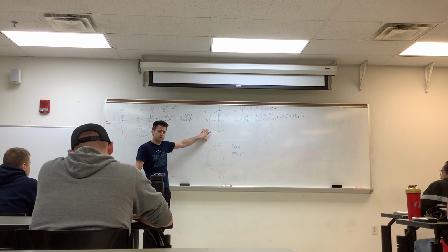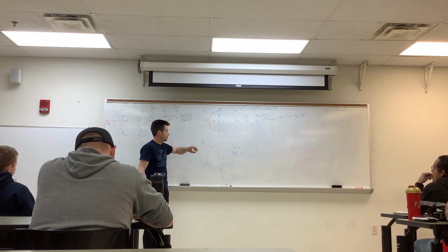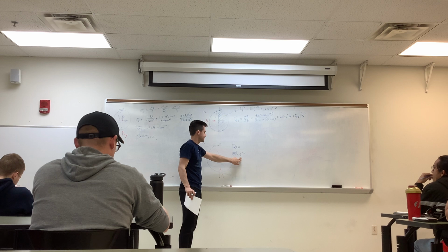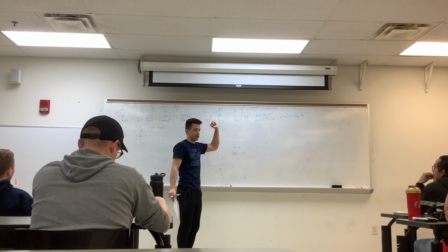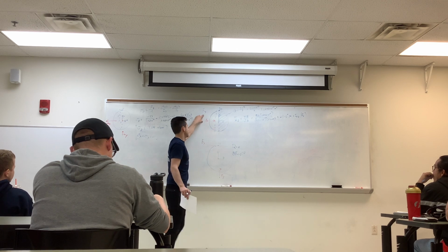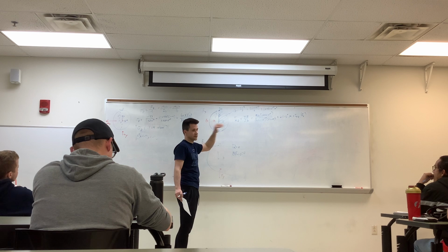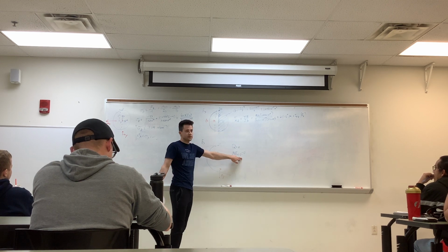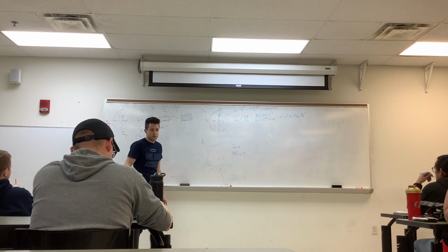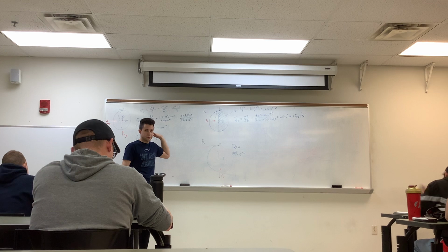Any kind of question with these two separate ones? How do you know that you're doing XZ versus YZ? So the second letter here is always the one coming out of plane. Right. So in this case, the z-axis coming out of plane. The first one is the direction at which your force is acting. Okay. So this first one, since it's our force in the x, it's xz. This one, since it's force in the y, it's yz. Okay. This is going to clear up some things with regard to shear flow.